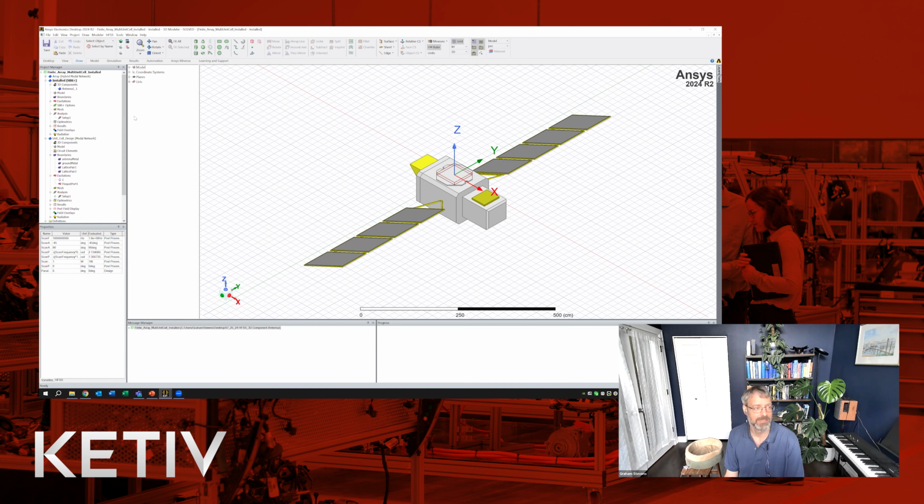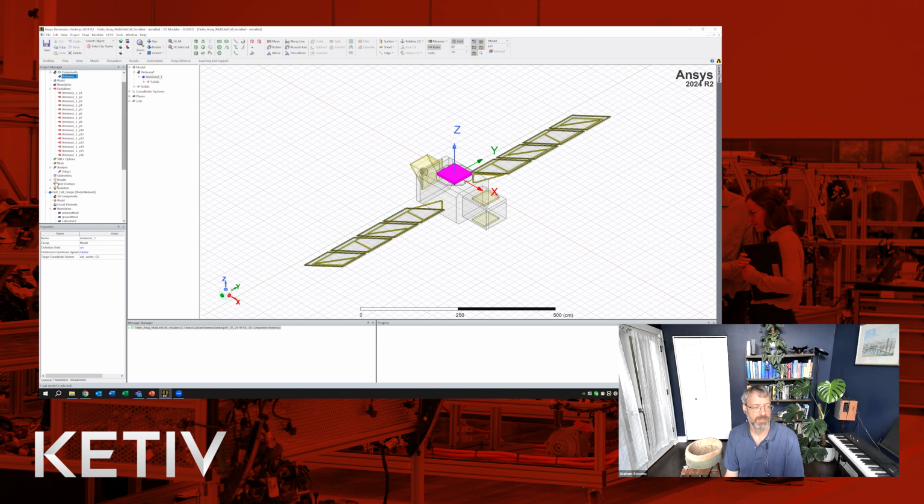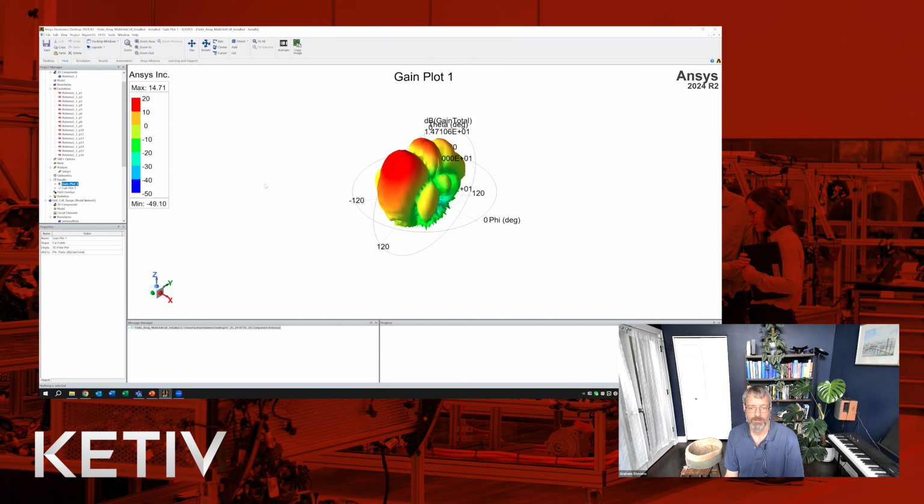So this is the satellite here, where we've taken this antenna and imported it, where you create an antenna and link to source design. So we've got the design modeled as the antenna here. In this case, we're linking to the source design for the near field output to then run an SBR analysis to again model that antenna in its environment.